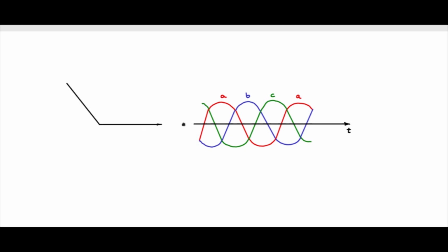So let us say I have three axes: A axis, B axis and C axis. They are distributed spatially 120 degrees apart, or 2 pi by 3 radians apart. Let me also draw the negative portions of the axis in a light color. B phase is 2 pi by 3 radians apart from A. C phase is 4 pi by 3 radians apart from A, all measured anti-clockwise.